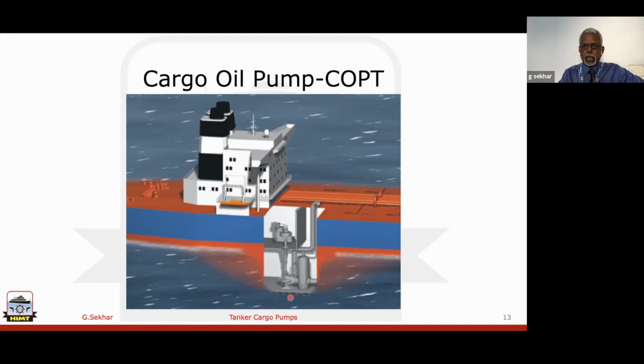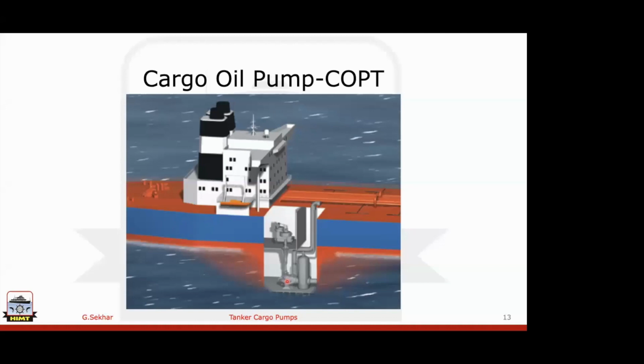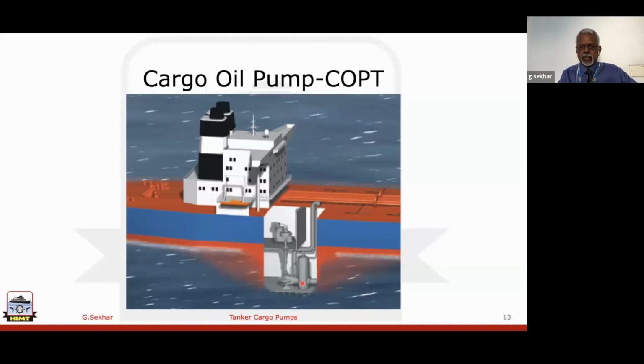Nowadays, the pump room also needs to have a double bottom as per the present MARPOL Annex 1 requirement. So the pump is here and your turbine is here. And the watertight bulkhead, even though we are not to have any opening there, here we have an opening because the shaft has to pass through. Of course, we have to have seals there, bulkhead seals. And the location of the cargo pump is here. And you'll find there are pipelines on the suction side connecting to various tanks.